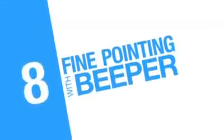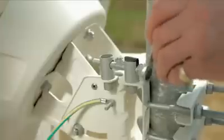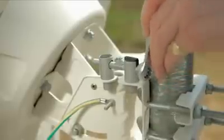The fine pointing of the antenna is the same procedure whether you found the satellite with either the KU pointing tool or the beeper and inclinometer. The first stage is the azimuth fine adjust. You verify that the two azimuth locking nuts are loose. You must pass the maximum signal level in both directions to allow the modem to measure the maximum signal to noise ratio.